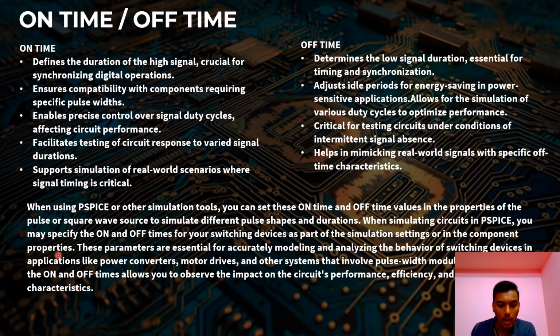The meaning of this is that you can change the on time or off time in the simulation settings. These parameters are essential for accurately modeling and analyzing the behavior of switching devices in applications like power converters, motor drivers, and other systems.